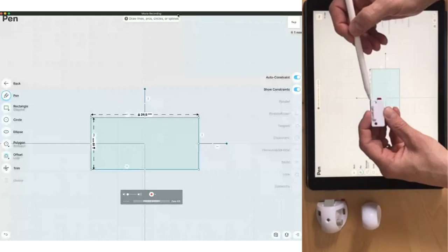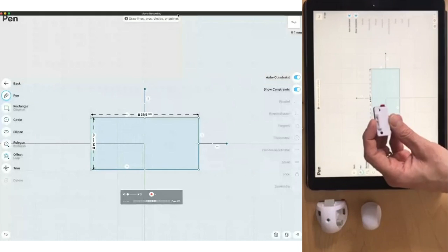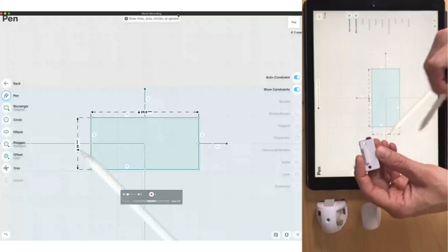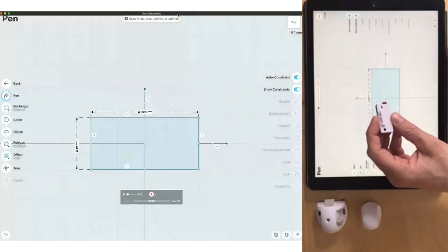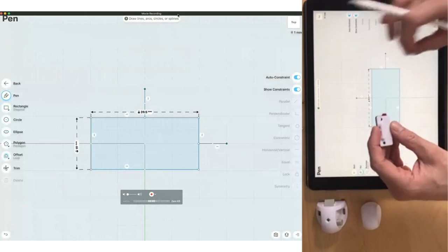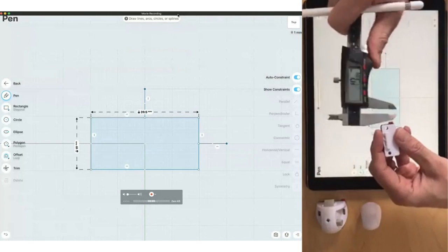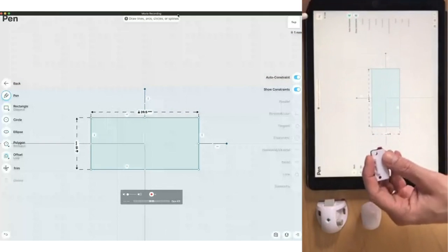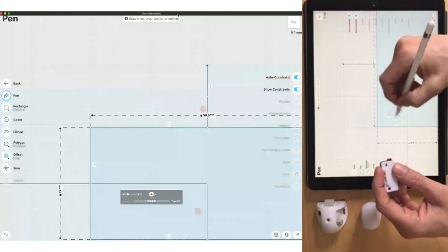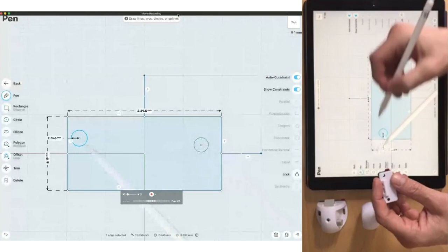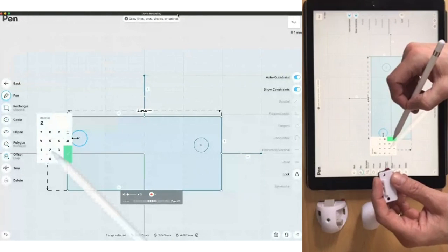The rounded corners I will actually not model in the sketch. I want the sketch to be very basic, because that makes adjustments much, much easier. The holes, however, I can put into the sketch. So also here, let's measure. That's around, let's say, 4 millimeters. So I can make myself a circle, and a circle somewhere, and say this is a radius of 2.